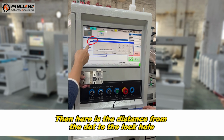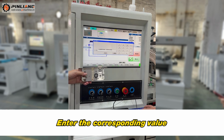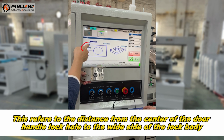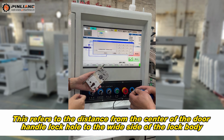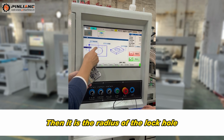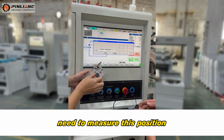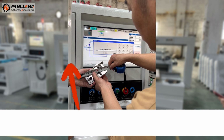Then here is the distance from the dot to the lock hole. Enter the corresponding value. This refers to the distance from the center of the door handle lock hole to the wide side of the lock body. Then it is the radius of the lock hole. Need to measure this position. It is the distance measured by a ruler.